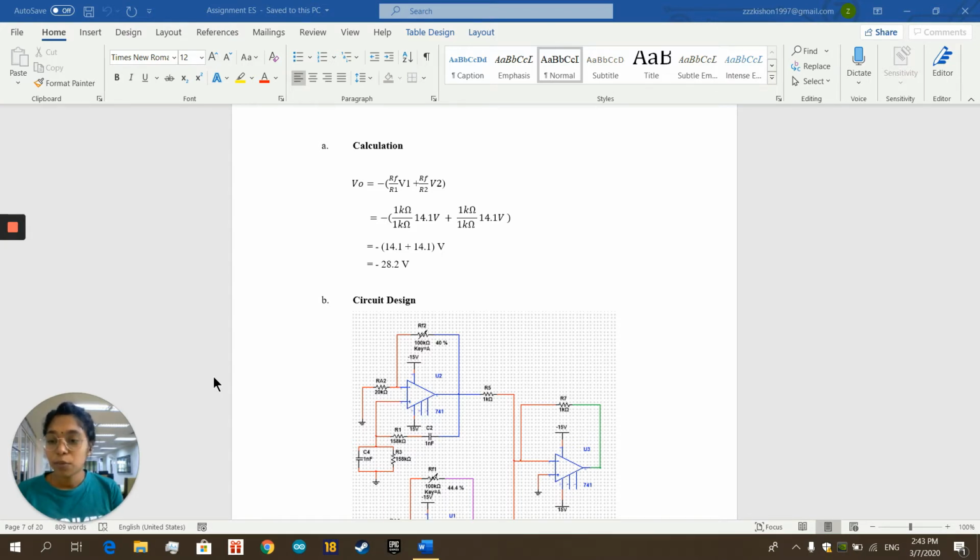First of all, voltage summing is an op-amp, operational amplifier, circuit that we use to combine voltages from two or more input voltages to make a single output voltage. That is why we used voltage summing in our circuit, where we used it to combine voltages from the oscillator 1 circuit and the oscillator 2 circuit before further proceeding with the output voltage.